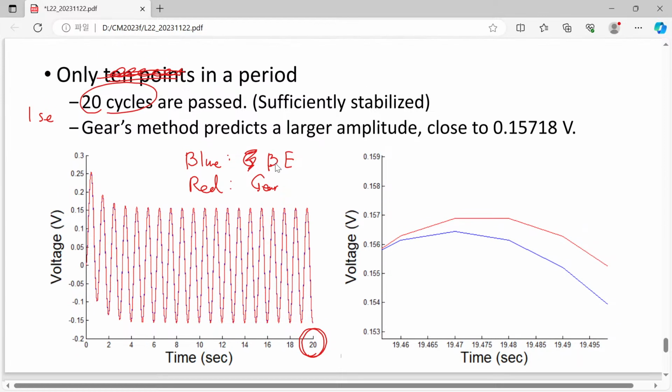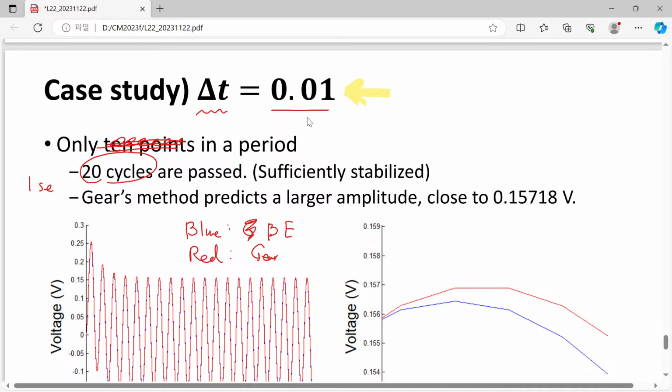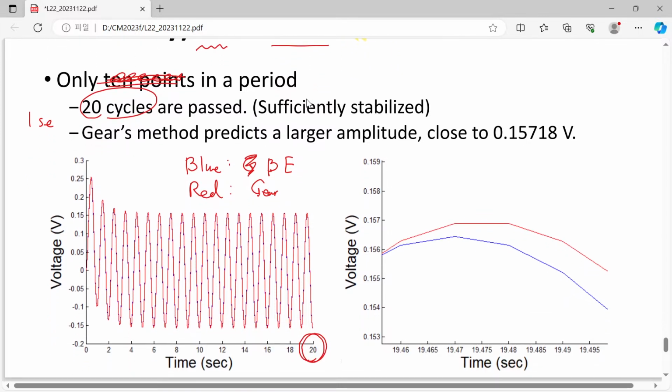For this value, it looks already good. Initially we have a certain transient behavior. After that, this is gone, and now we have a well stabilized response to our input signal. Since we have applied a sine signal, we can expect a sine or cosine signal with the same frequency.